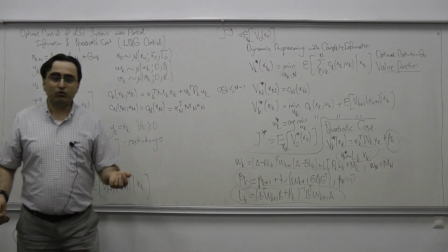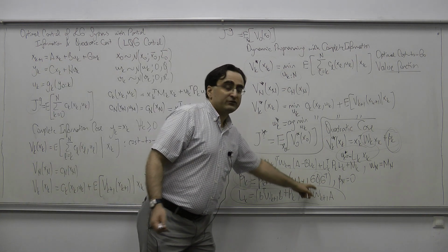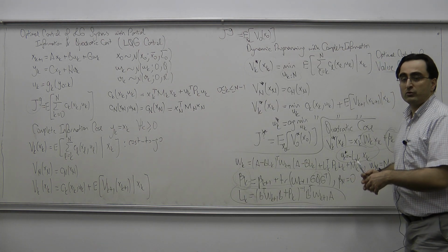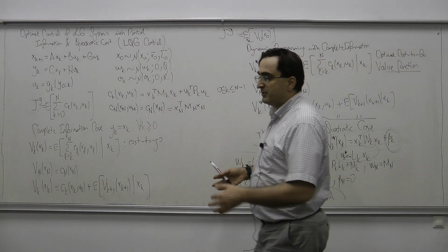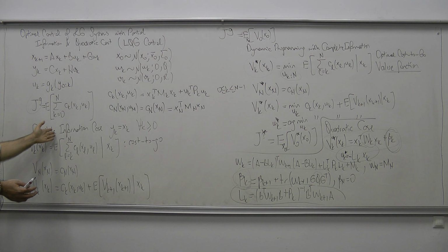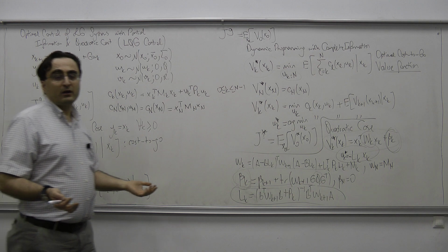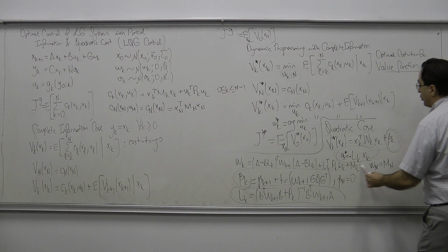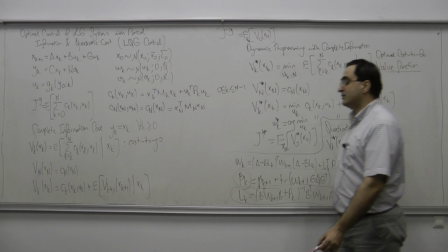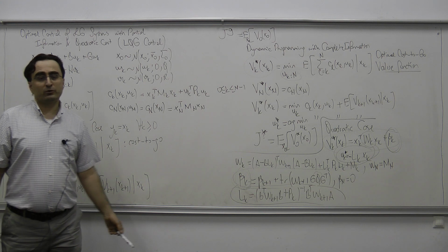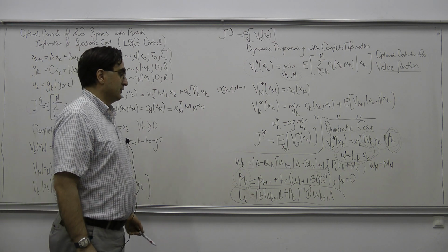And actually you can show that if I increase Q, then the value of the optimal cost is going to increase because the system is then more uncertain, and in that case the cost that we obtain is going to be larger. All right? But the control rule or optimal feedback policy that we find at the end is independent of the process noise covariance.